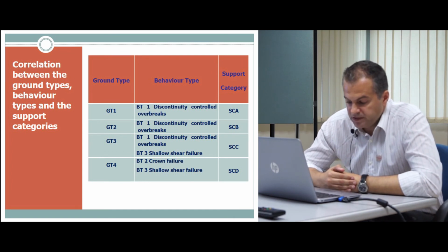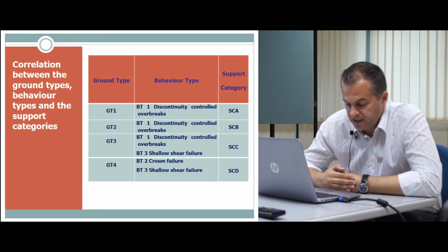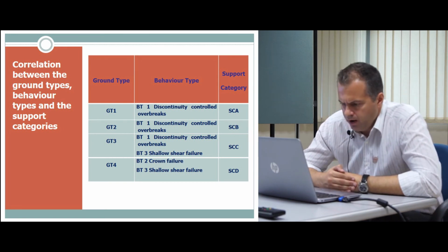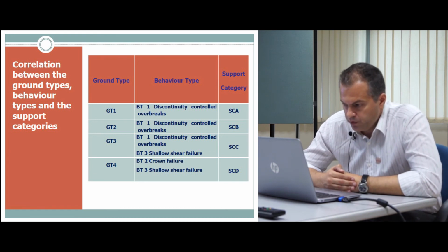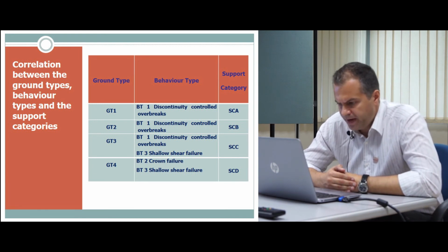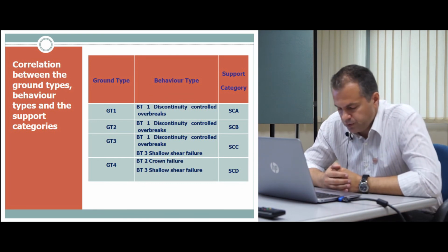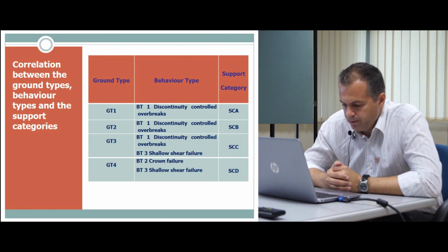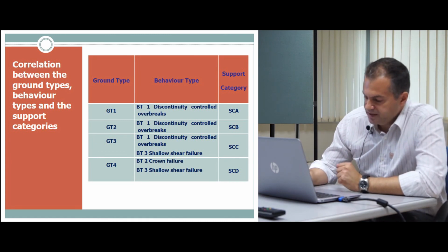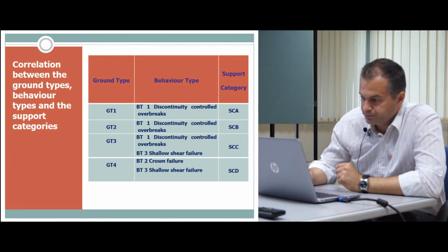So we need some face stabilization measures, and of course some small extrusion of the face in the last case of the shallow shear failure, also depending on some small fracturing, heavily fractured face. Some small blocks may also slide and break from the face.